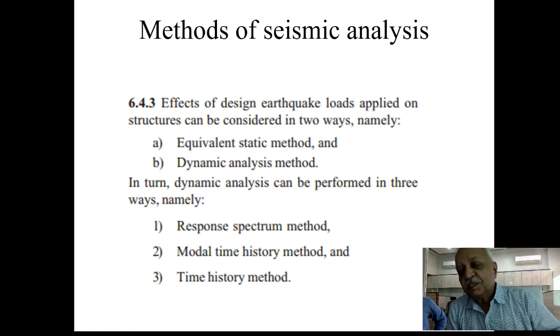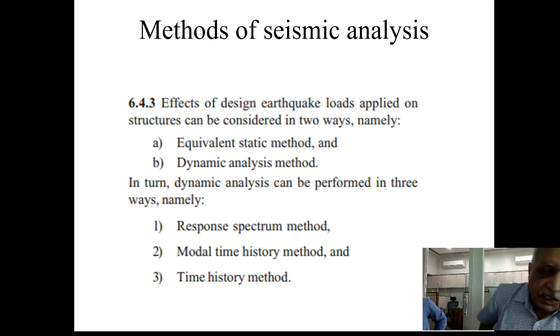The methods of seismic analysis which we are following, basically we are considering the equivalent static method, which we will see briefly, and then the second method is the dynamic analysis method. The dynamic analysis method has got three options. One, you can use the response spectrum method, or the modal time history method, or finally the full-fledged time history method.